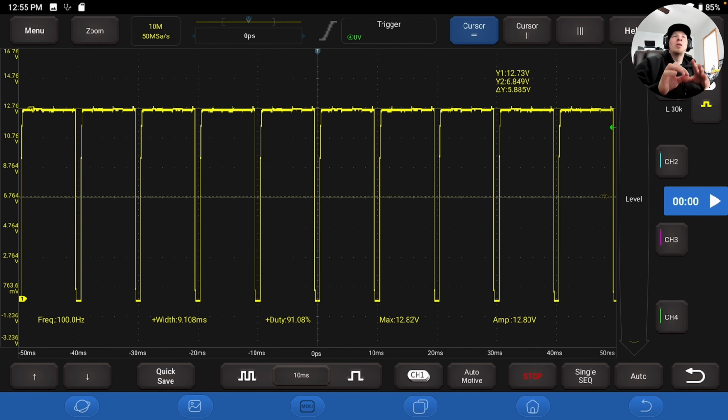But again, you need to be sure of this before you make a recommendation to the customer, because you need to understand how the system works. And that wiring diagram didn't tell us anything about, hey, this is a pulse width modulated power supply. It just showed a power and a ground wire, nothing else. But we do know that all components that are doing any work have to have a power and a ground.